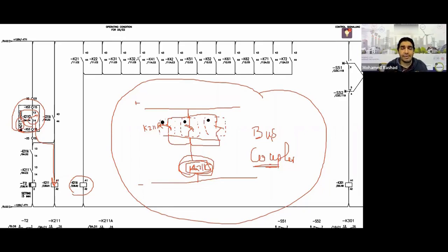Now I have activated the disconnector, the first disconnector I have, so KT1 has been activated. When KT1 was activated, it activated the actuator named K211. Nice, you told me nice, K211, what is that? In the bus coupler, it closed its contact here in the bus coupler, so it activated K211C. K211C is now activated, so I have a signal in my cell.